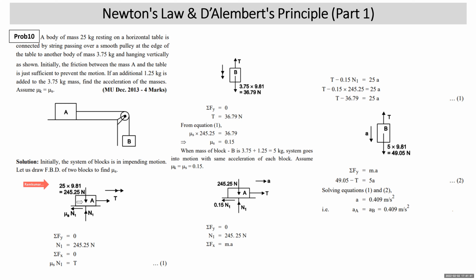Now, in this problem, as it is a problem of statics, I just repeat that sigma Fy is equal to 0, N1 is 245.25, and sigma Fx will not be equal to Ma, it is sigma Fx is 0, because it is a part of statics. So T is equal to mu s N1. Put the value of N1, and you can get the value of mu s.